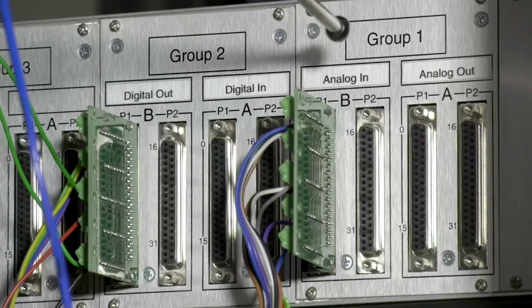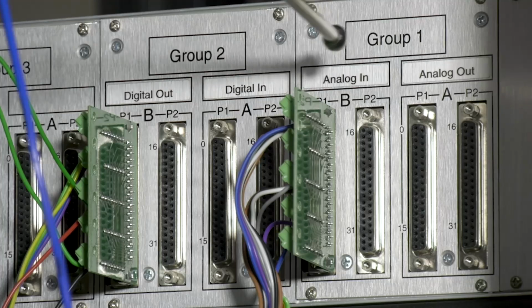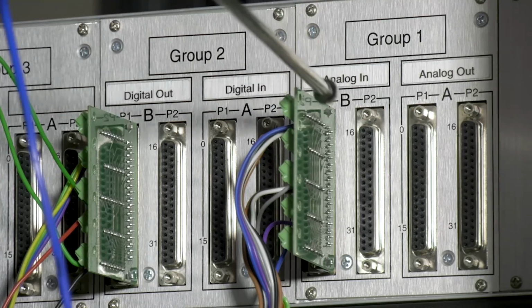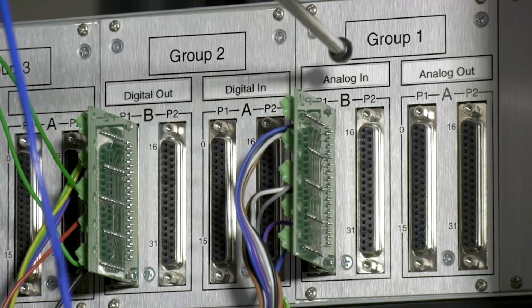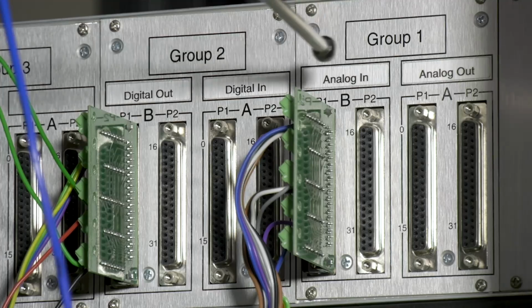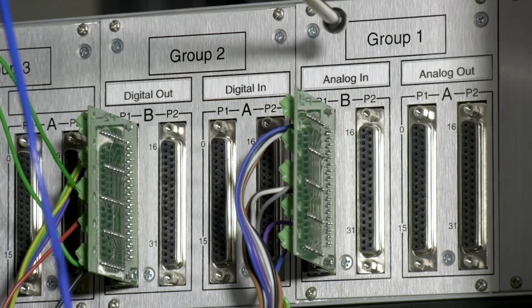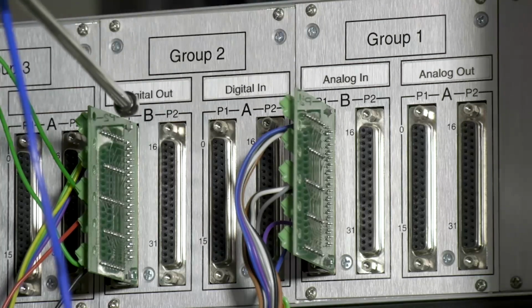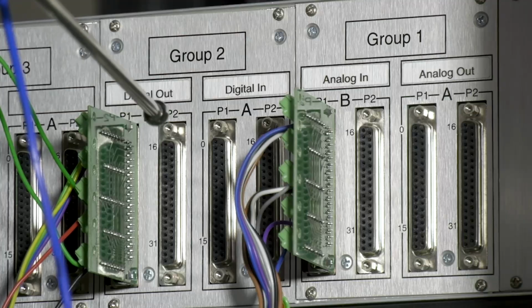To perform rapid control prototyping, we need to access the analog input output pins, which we generally call analog input outputs. The model of Opal RT that we are using is OP5700. In the video, we can see 16 analog inputs, 16 analog outputs, 32 digital inputs and 32 digital outputs.